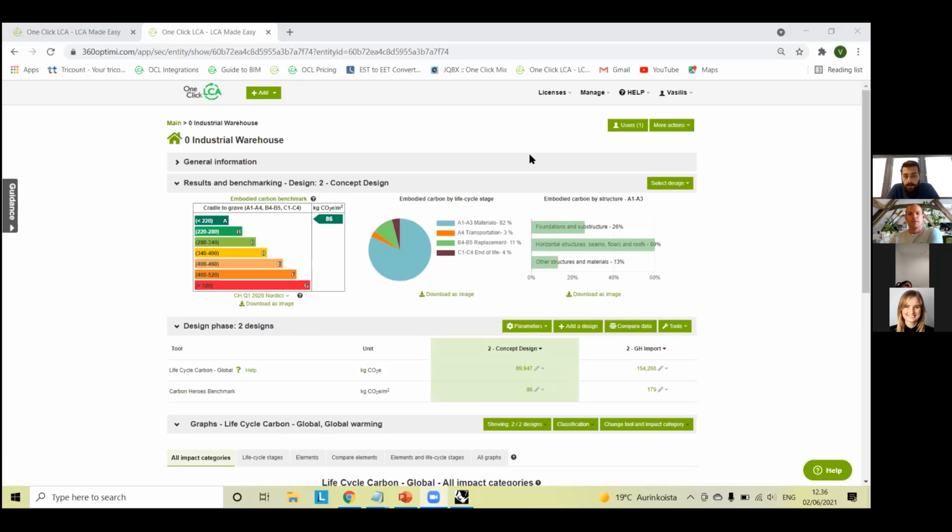Yes. So if I'm not mistaken, SketchUp can export the data in an IFC format, and we can basically read any IFC file. Sorry, that's IFC, is it? Yes, that's an IFC file. Okay. So you can pull this data into Solibri, for instance, or any IFC reader, and then upload it from there to OneClickLCA. Okay, fine. And that gives you the fundamental geometry and volumes that you've used in those models. Yes, all the data that you have used in these models will be sent to OneClickLCA. So quantities and material descriptions will be sent to OneClickLCA, and then the mapping process would be done automatically.